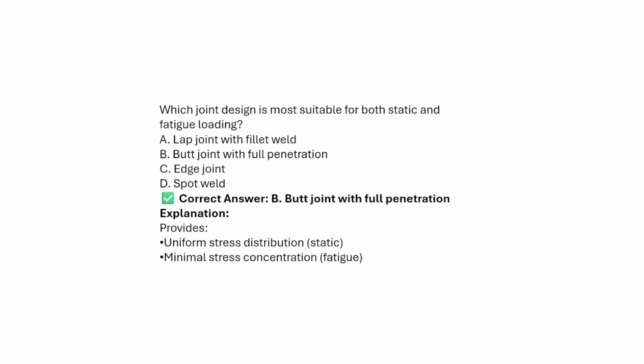Which joint design is the most suitable for both static and fatigue loading? Option A, lap joint with fillet weld, butt joint with full penetration, edge joint, spot welding. The answer will be butt joint with full penetration. It provides uniform stress distribution and minimal stress concentration.